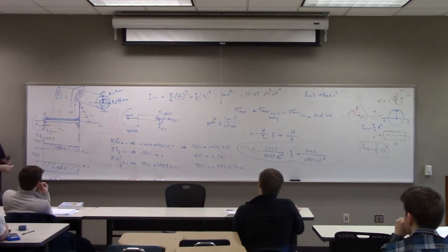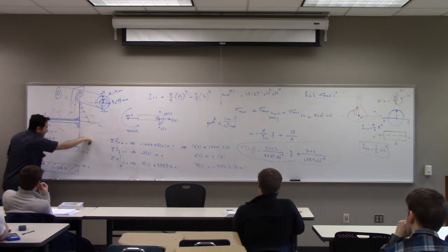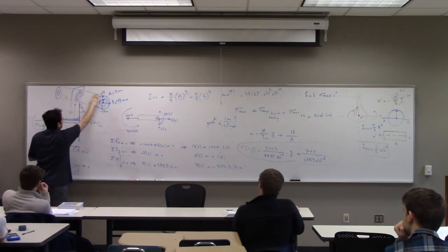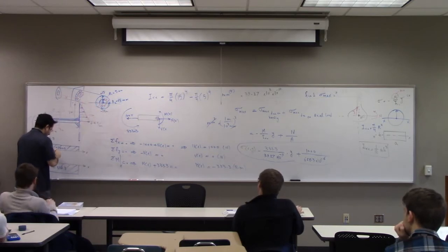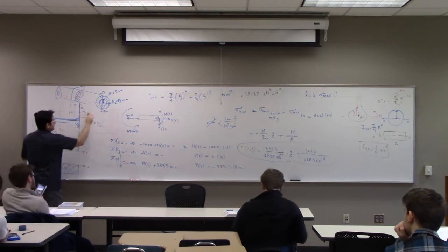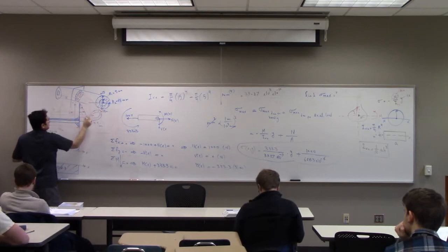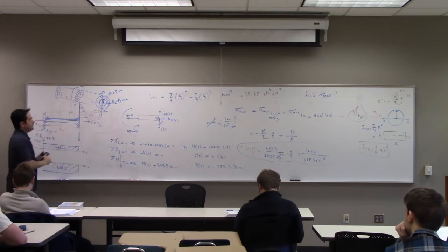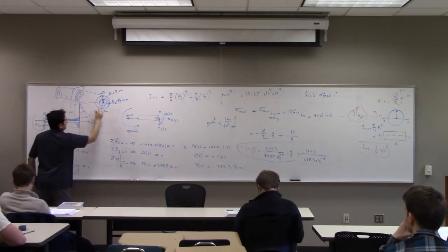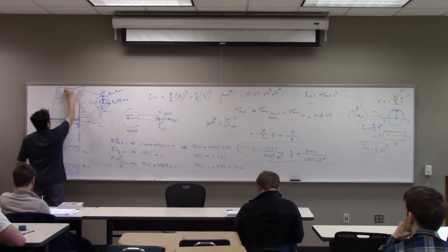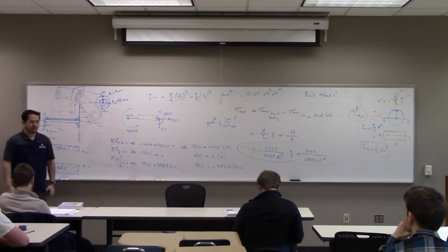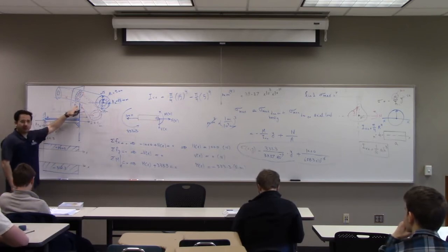And it kind of makes sense because the moment you actually apply this bending moment here on the rigid plate, this is going to go nose down. So that means this bar is going to go down. Hopefully I can make a little graphic here. So it's going to go like this. And then you see everywhere along this top line you have stretching. And here you have compression.